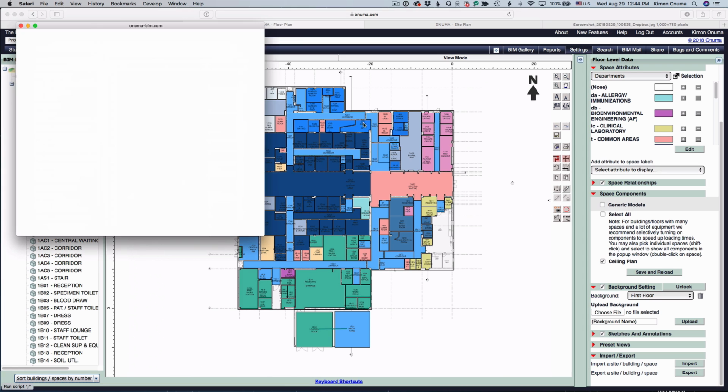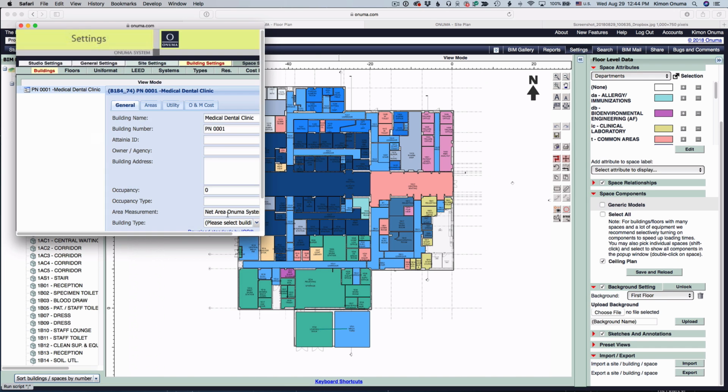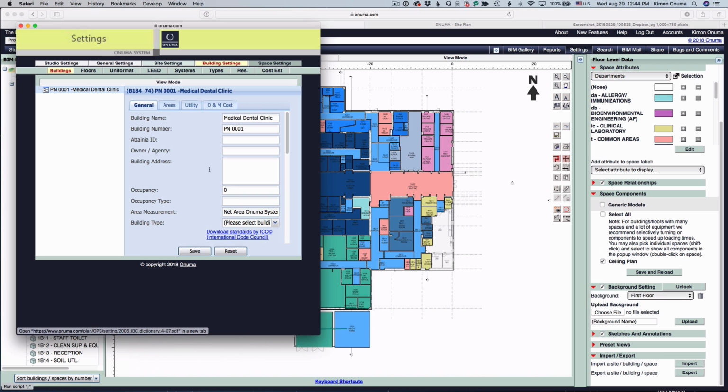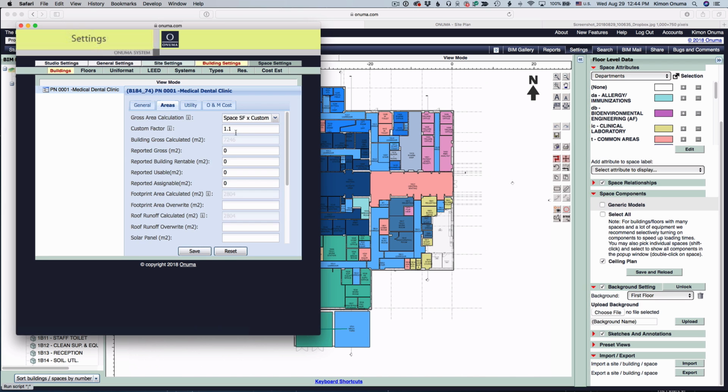You can also adjust the settings. So if you go to the settings tab, all of the assumptions, for example, of cost or areas, the area in this particular building could be calculated by the outline floor slab for the gross area, or you can go to individual spaces and get a net to gross factor if you're in early planning.